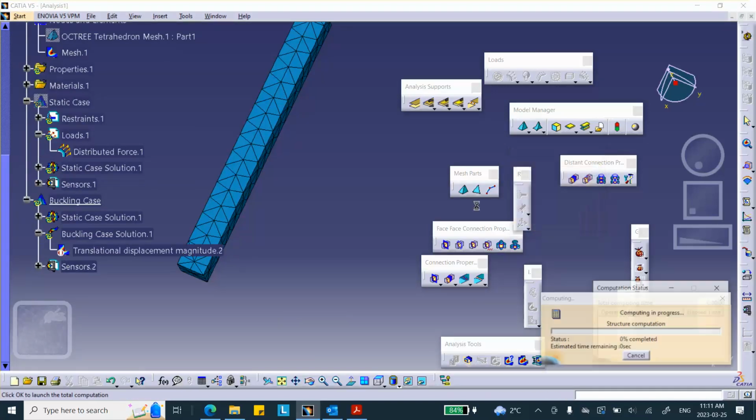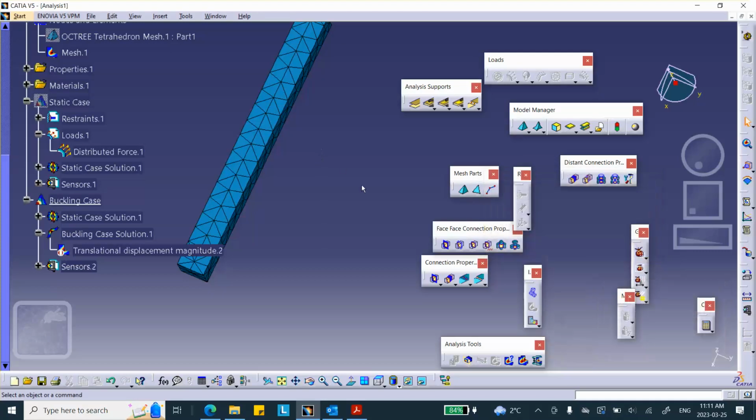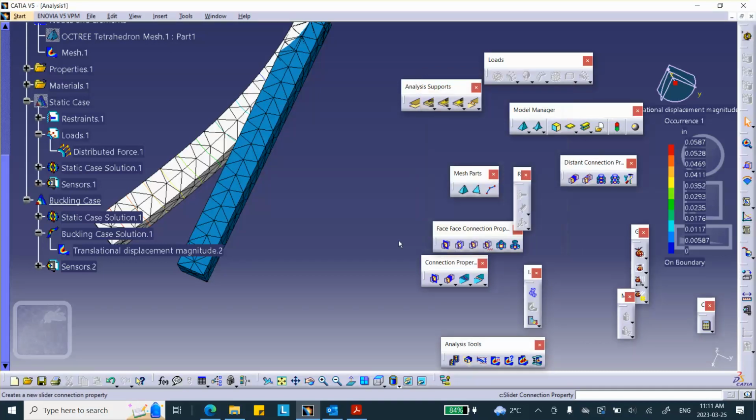I don't think it's going to make that much of a difference. You're going to be in the vicinity of that 22,000. Okay, so double click. Yeah, 20,000, 21,000. Didn't make any difference. Okay, so I made a boo-boo here and used steel instead of aluminum. Obviously, a bad mistake. But it agrees. The results agree with the Euler buckling. Good luck.